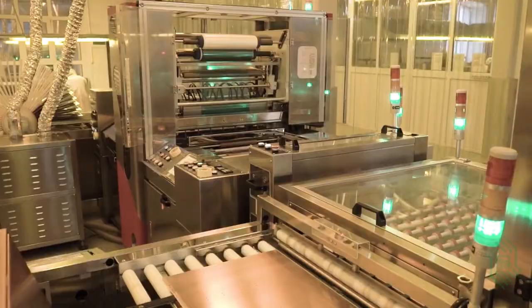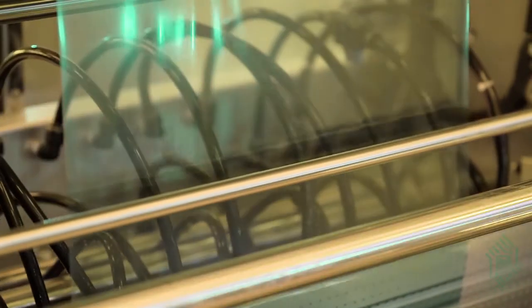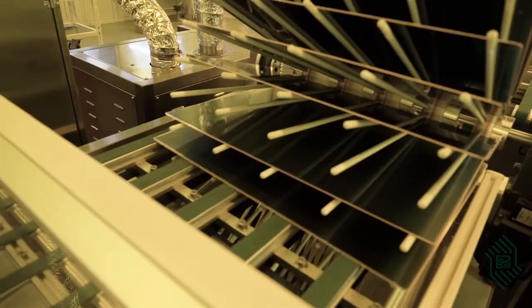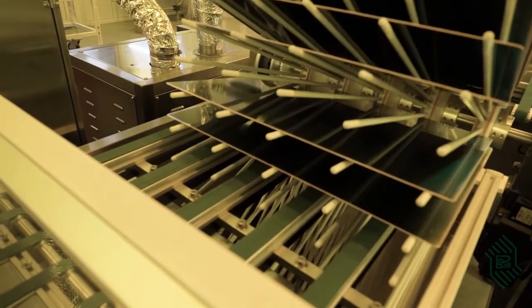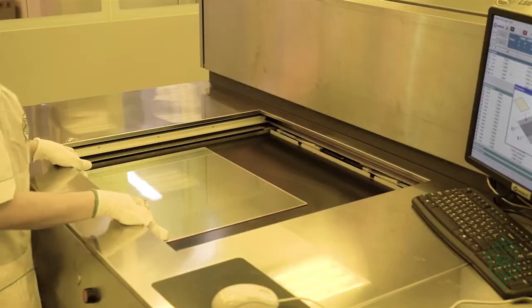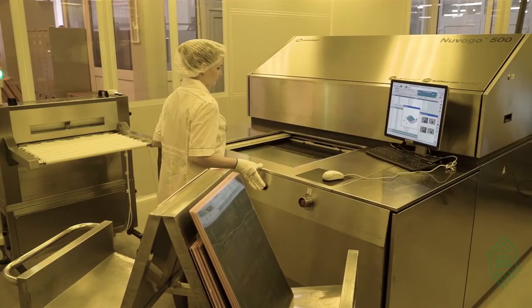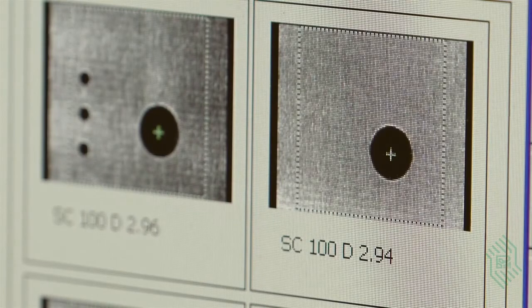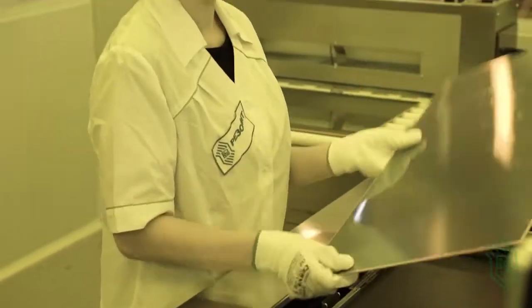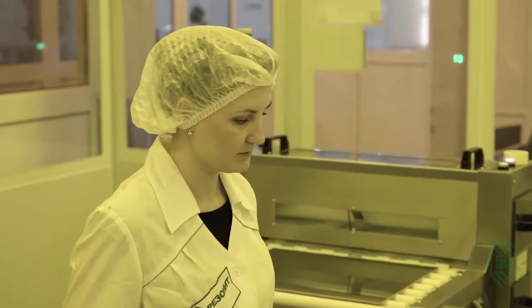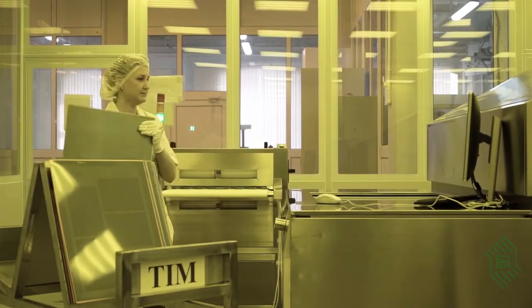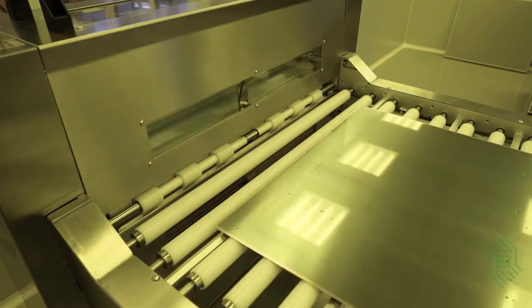The photoresist is applied on the automated lamination line. The panels are gathered into a cassette and transferred to the imaging area. The direct laser imaging machine identifies the registration holes using optical cameras and verifies their location and diameter. If the panel complies with the quality criteria, the photoresist is selectively exposed with a UV laser.